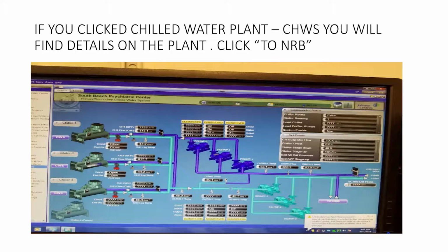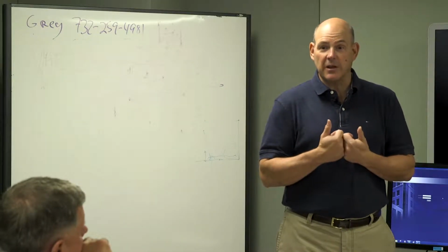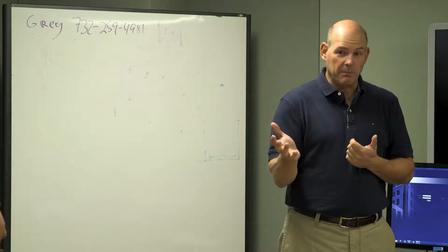So you should not have to change the set points. The only time you change the set points, like I said, is if you wanted to change the chill water temperature, because eventually a balancer comes in and tells me those numbers. So I put those numbers in, like for the differential pressure set point.